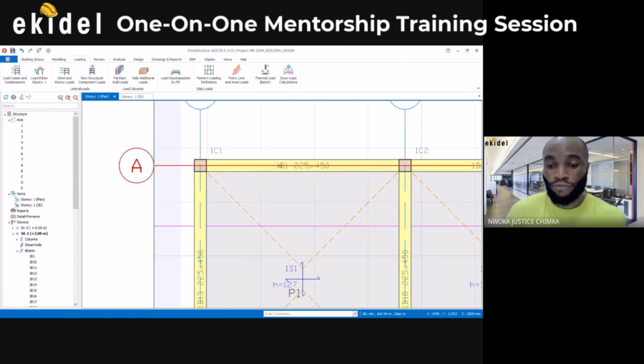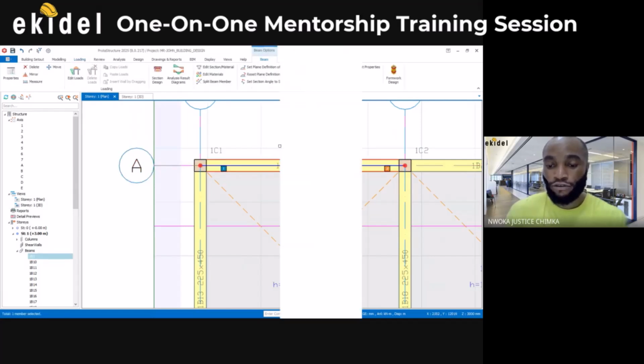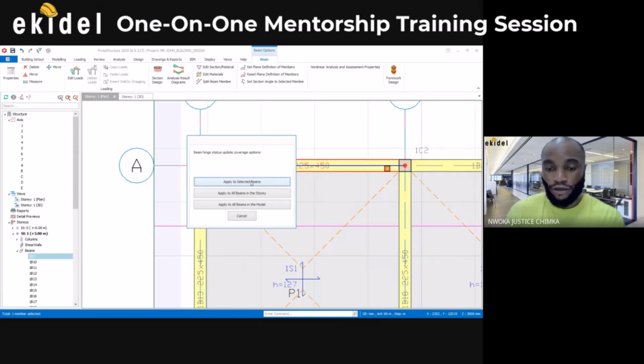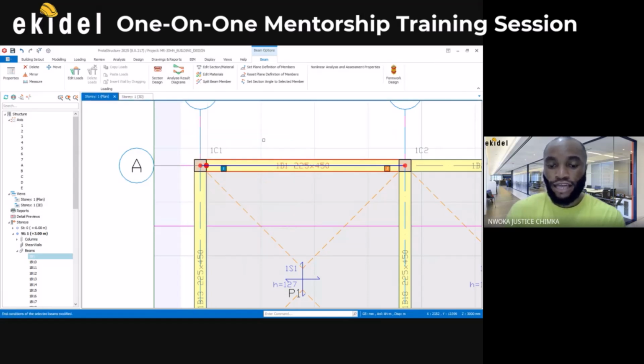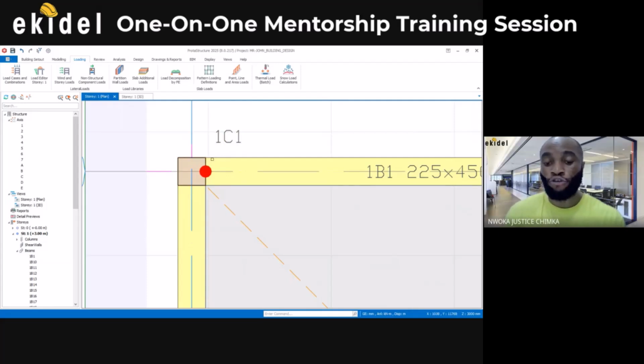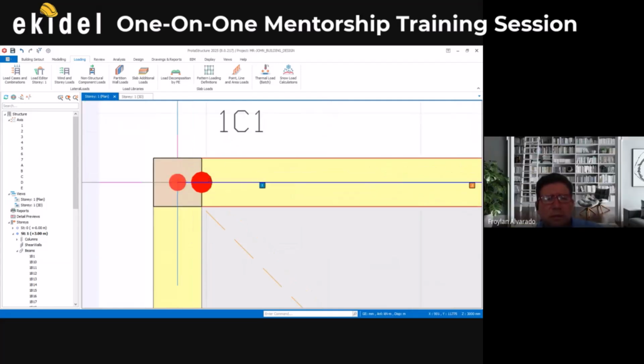So I'll click on the beam now, right click, and then you see here, update beam end condition. I'll come now and say hinge at left, which is I. I'll click on it and say yes, apply to selected beam. I see that it's now showing 0. Yes, it means that the moment at this end now becomes 0. You understand? That's what this means.